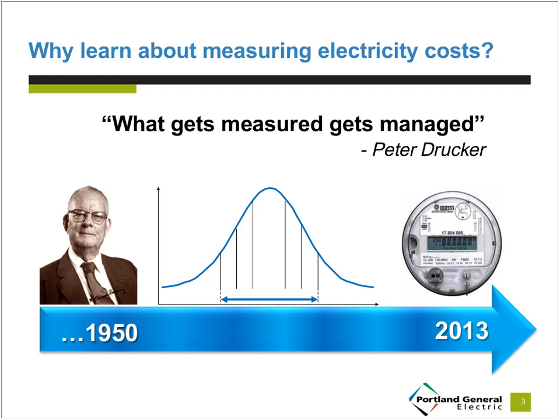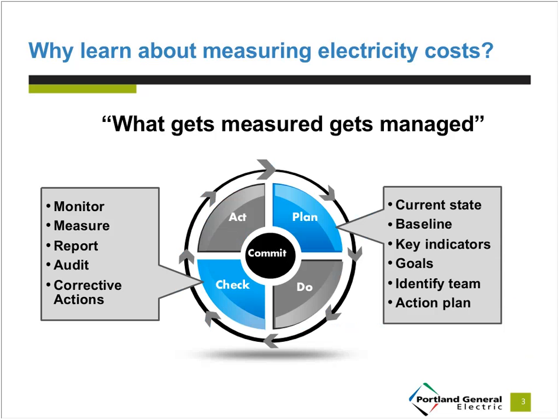A place to start with measurement are the labels on the box or nameplates on the equipment, which are required by federal code and must include information about the electrical requirements of the equipment. For electricity, the universal measurements found on these labels are watts, volts, amps, which we will discuss in the following slides. Once you have purchased the equipment, these key measurements of electricity are locked in and are difficult to change without expensive replacement or retrofit.